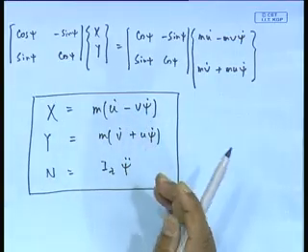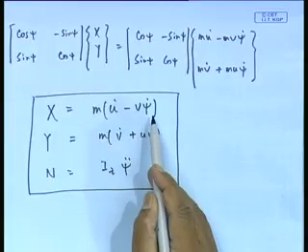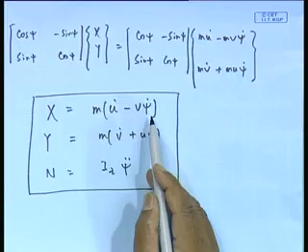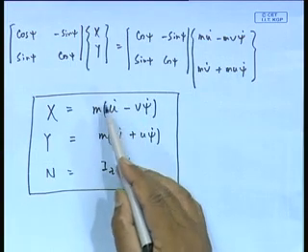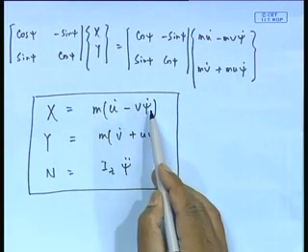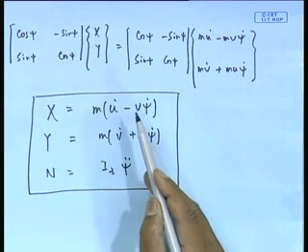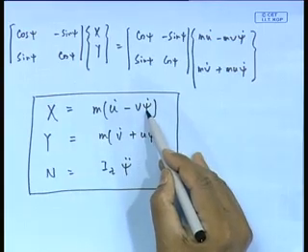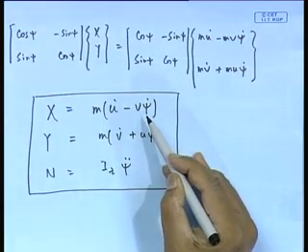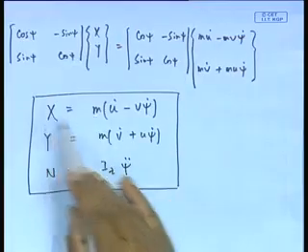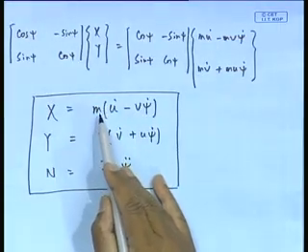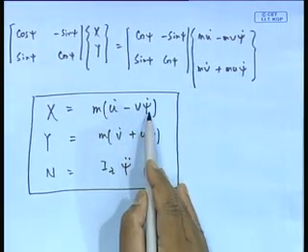That is what is called lateral acceleration, m v psi dot or m v r. It is like your Coriolis force, rotating frame of reference, similar to that. This is the important point to recognize. If psi dot was 0, of course force is mass into acceleration, they translate to each other. Y is same, no question of n comes in. Some people will write psi dot as r, rotational velocity. So, you find x is mass into acceleration and an additional term, additional force comes, m v psi dot, m v r.